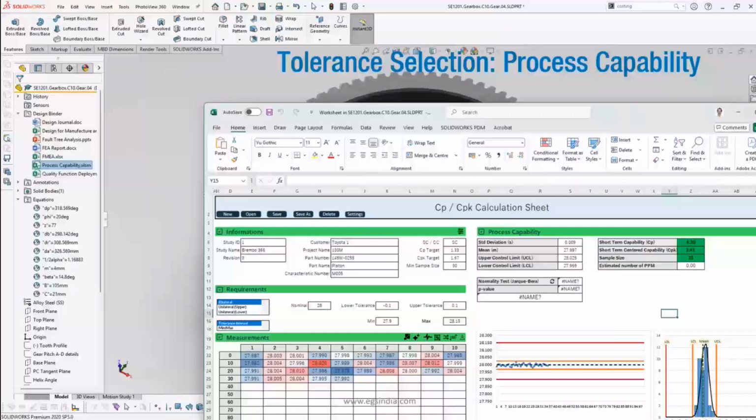So a lot of things can be brought in and stored in the Excel file. There is another tool called MITCalc. And also you have SolidWorks, which is having the TolAnalyst. You can use that to also do the tolerance stack-up analysis, to look at and incorporate the process capability to see whether the required process capability is available or whether the tolerances can be achieved or not. The control charts and the histograms can be seen right then and there. You see how powerful you can enable.